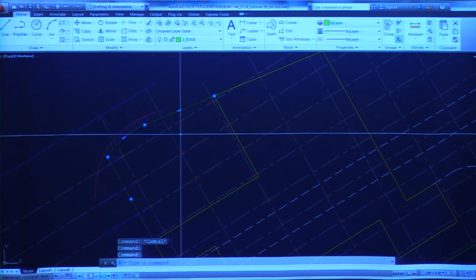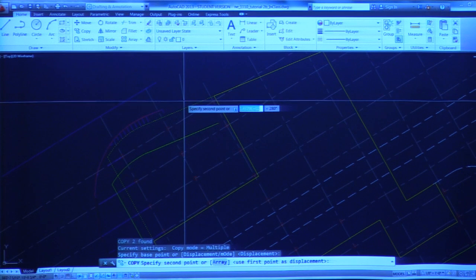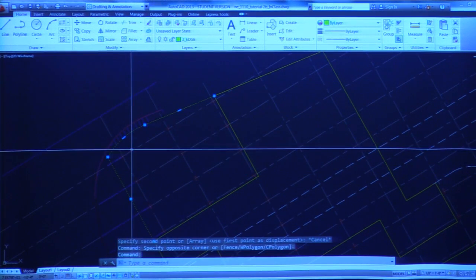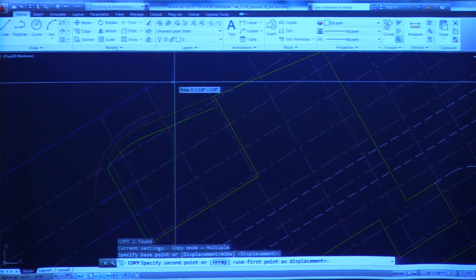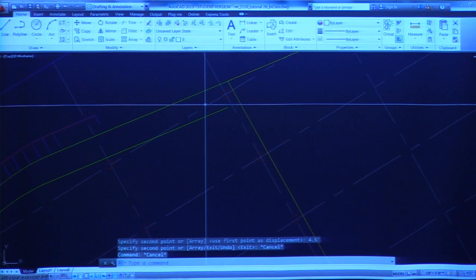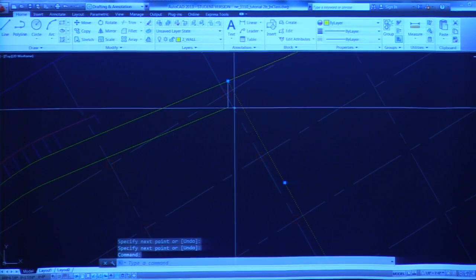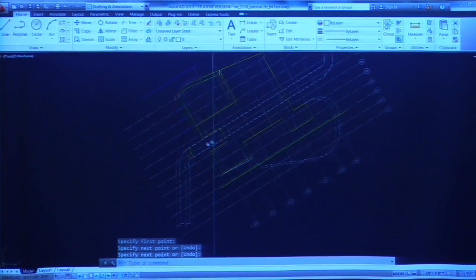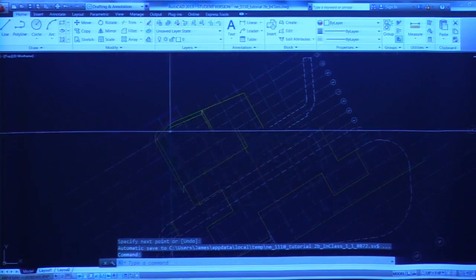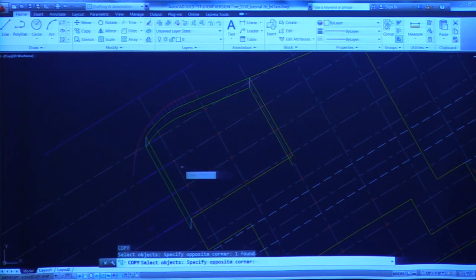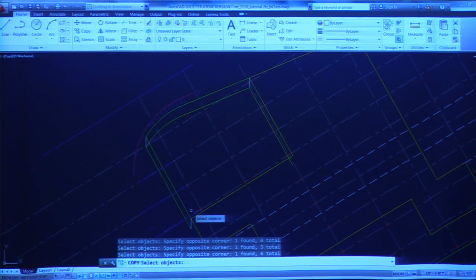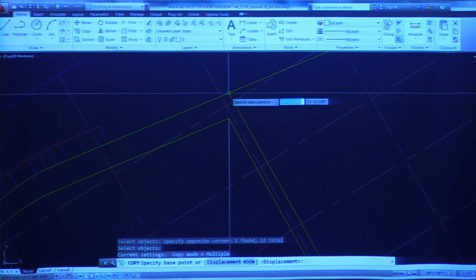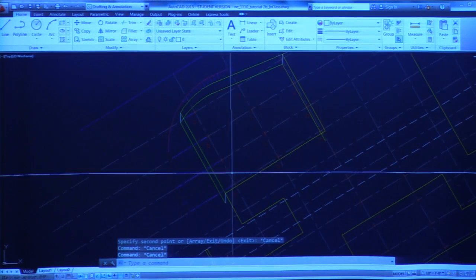So if I say that this is 4.5 feet deep, I'm going to copy this down 4.5 feet. My mouse moved, sorry. I'm going to copy that down 4.5 feet. And I can now finish that space out, as you can see. And so what this is starting to do is help me construct this in 3 dimensions. And then I can also take my column grid and copy that down 4.5 feet. And so those are the base of my columns.